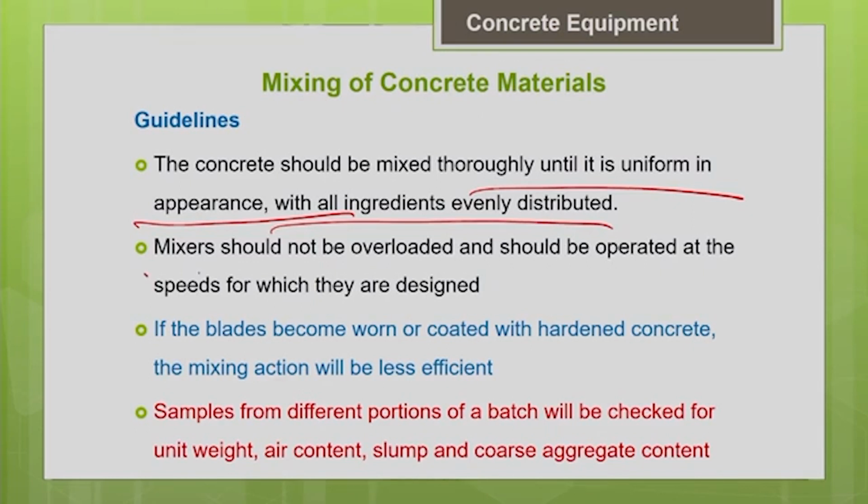The mixer should never be overloaded. If you overload it, the mixing won't be homogeneous, and it should be operated at the speed for which it is designed. As I told you, free fall mixers are designed for a particular speed. Power mixers are designed for a particular speed. You should go as prescribed by the manufacturer.